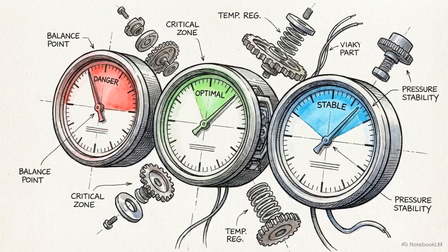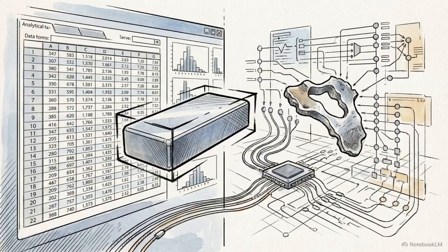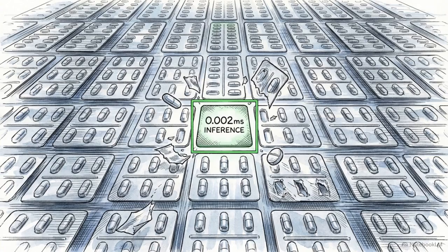At the algorithmic layer, engineers navigate strict constraints. They must balance latency requirements against data availability and the specific morphological complexity of the defect. This forces a choice between two primary pathways: extracting handcrafted features to feed a traditional classifier, or relying on end-to-end deep neural inference. High-speed operations, like blister pack inspection, operate on extremely low latency tolerances. These tasks require highly competitive, lightweight statistical techniques.